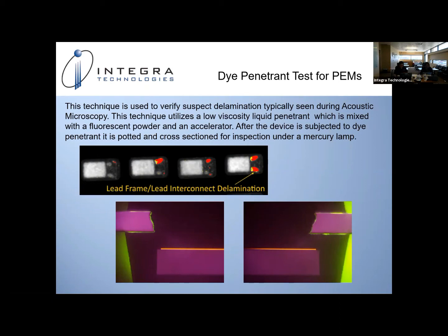No, the only other thing is, please go look at J Standard 020, 6.1, 6.2. It clearly says, in the very first sentence, that delamination, and call it a void, is not necessarily a failure. You need additional data, and Rachel rightfully stressed that if you suspect this device may have a real delamination, then do a dye penetrant test. So that's all I have to add, but if you have further questions, obviously I'll take them.